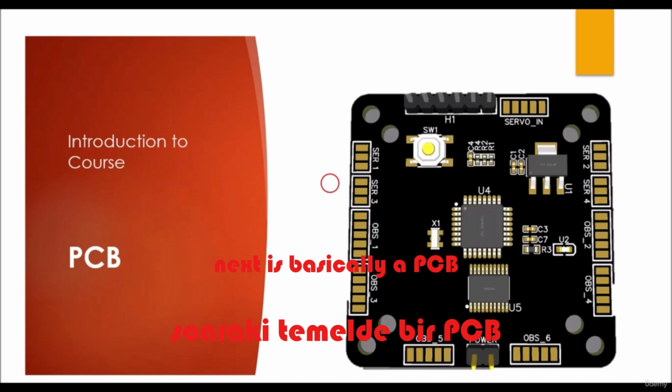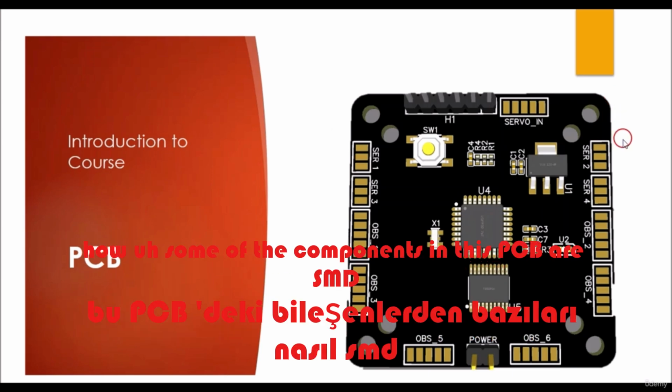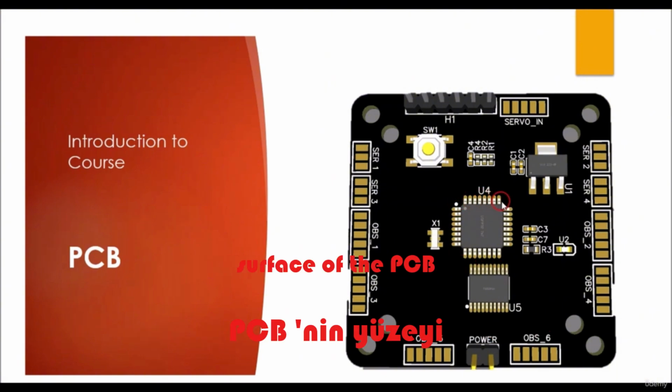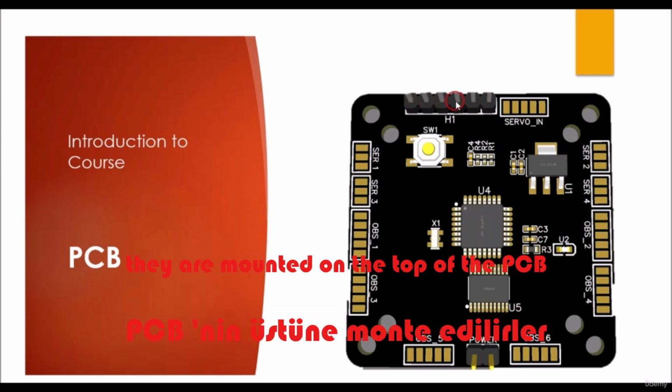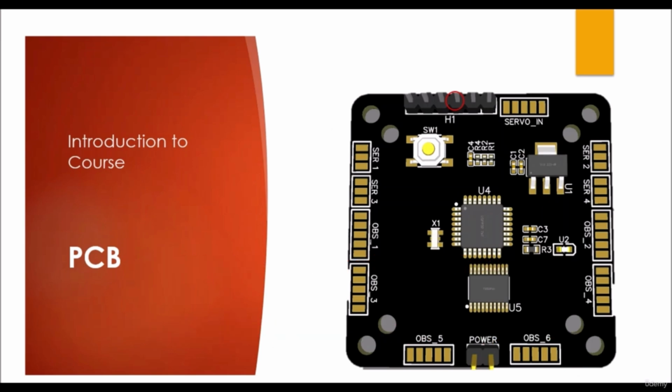Next is basically a PCB. It's a picture of a simple PCB, showing how the PCB looks, how some of the components in this PCB are SMD, that is, they are mounted on the surface of the PCB, and how some of the components are through hole, right? They are mounted on the top of the PCB, and their pins go right through to the bottom of the PCB.